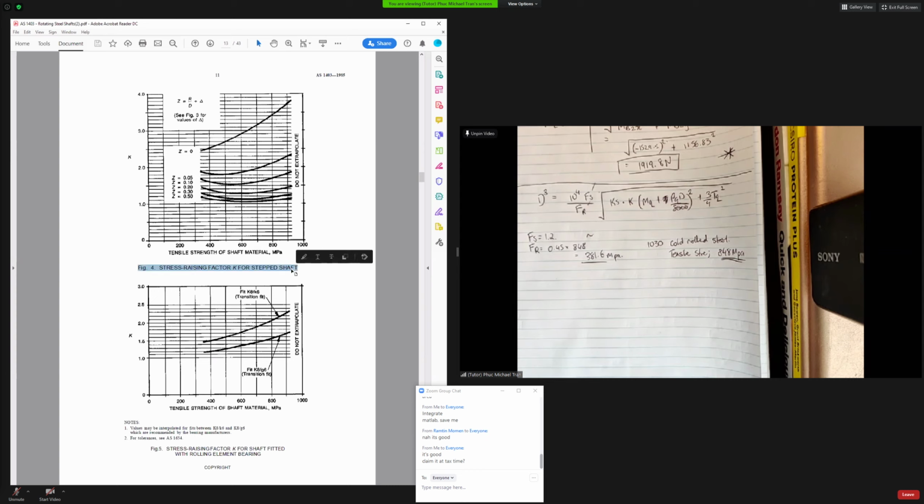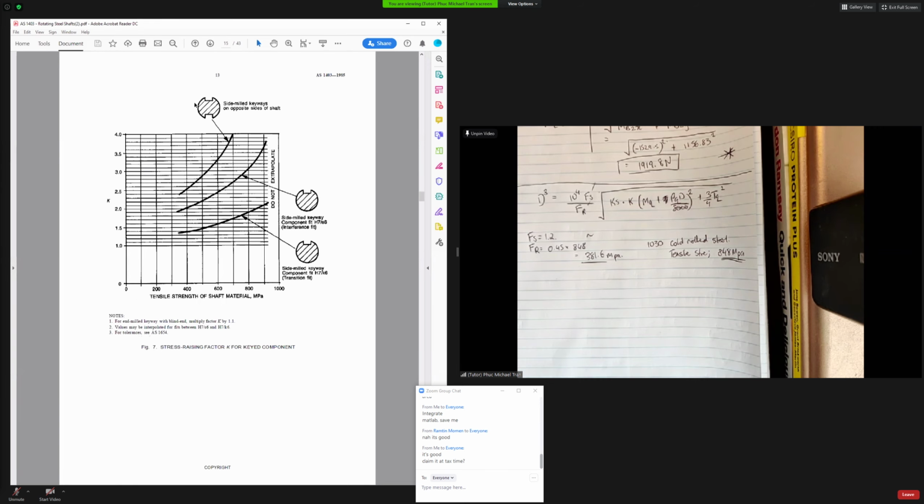Other characteristics you can have in a shaft could be keyways. They're pretty neat, but they're hard to machine. Depending on what kind of fit you have with your gear, you would have a keyway for the shaft and a key slot for your gear, and you just slot it on, and then it drives it, and it's pretty cool if you can get it right.